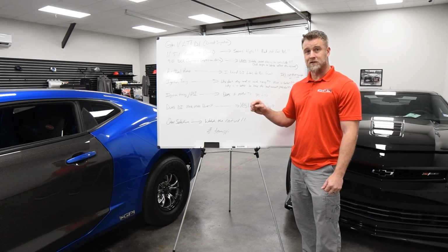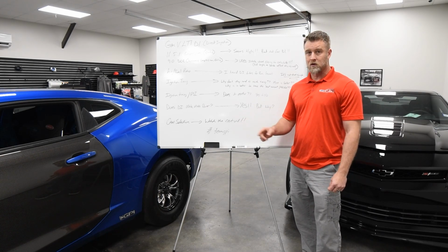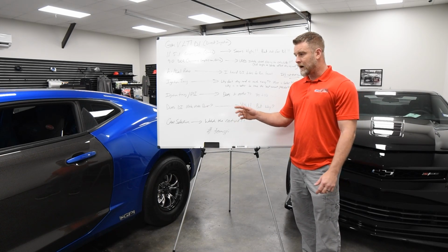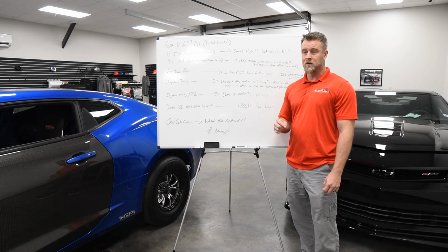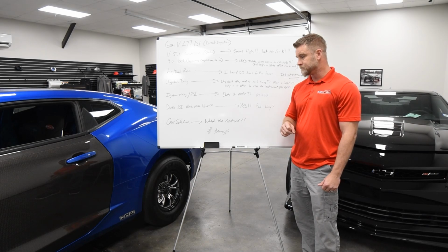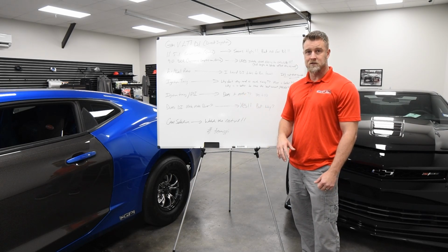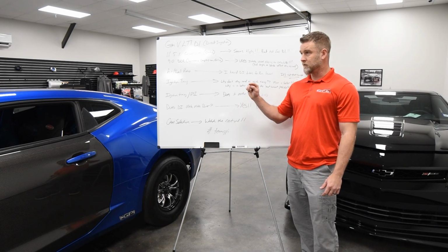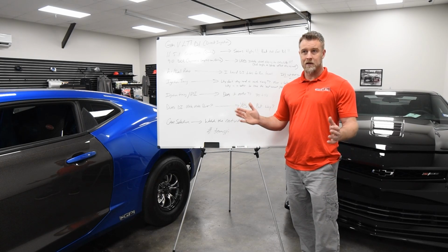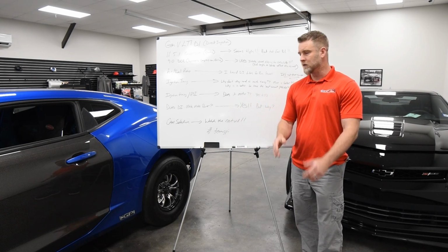when the injection event starts, I've never, even on our large cam cars with bunches of overlap, I've never made any power changing that. I've done it on the engine dyno, I've done it on the chassis dyno. Maybe it's just me, but I haven't found any merit in changing the start of injection event. But I have with fuel pressure tuning and making sure that my injection event is within a certain window.